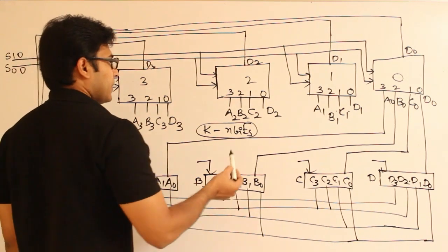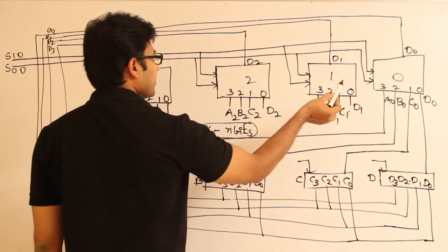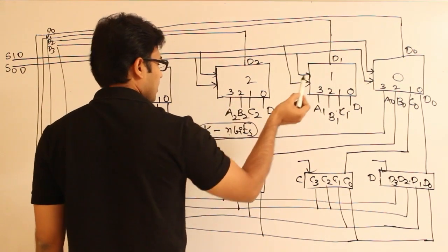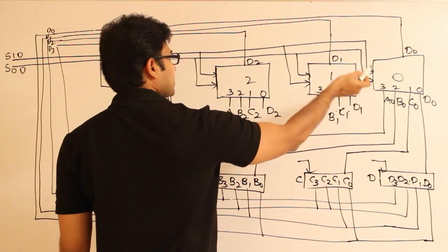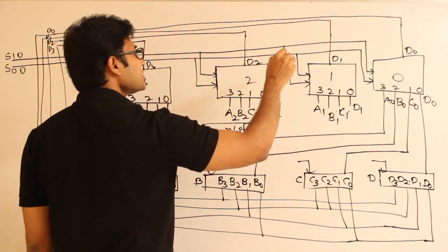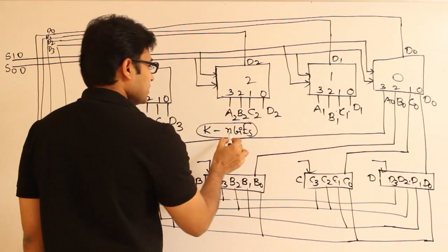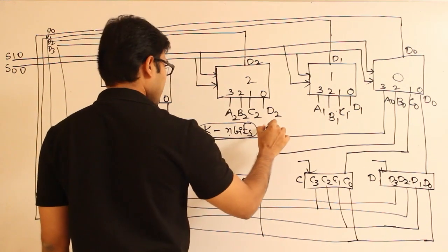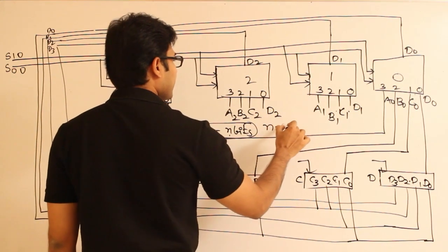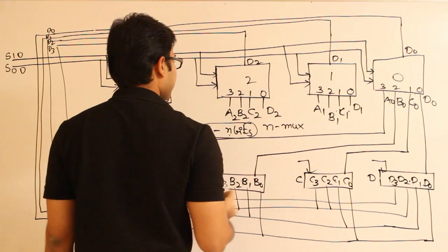So see this, now for every bit we need a multiplexer, isn't it? The reason is every multiplexer is going to provide into the bus 1 bit from the register. Since there are n bits, how many multiplexers we need? We need n multiplexers, right?